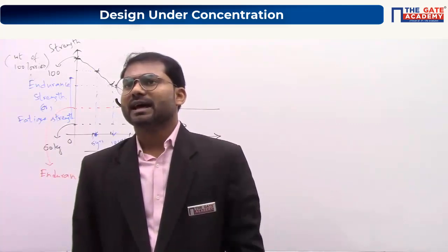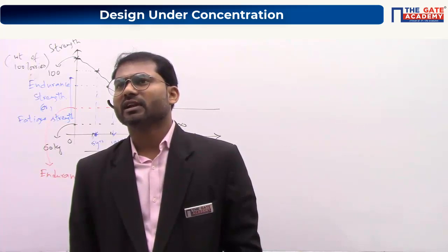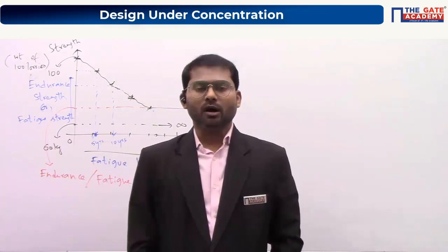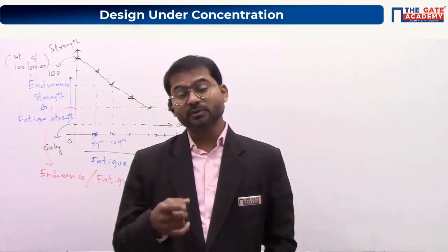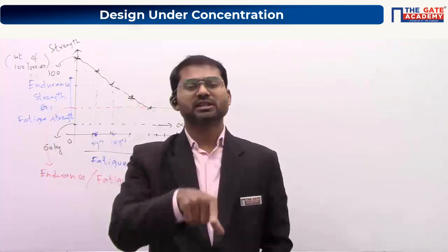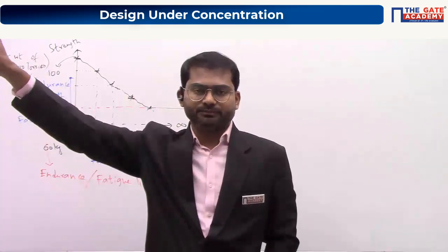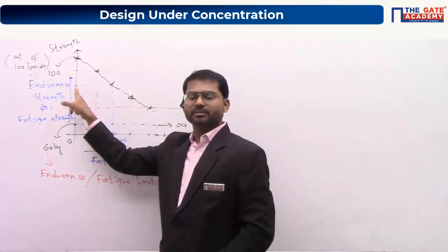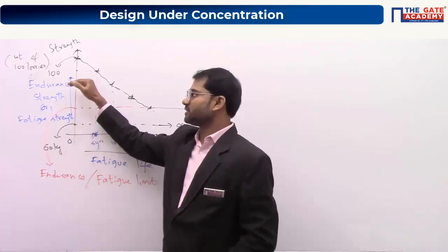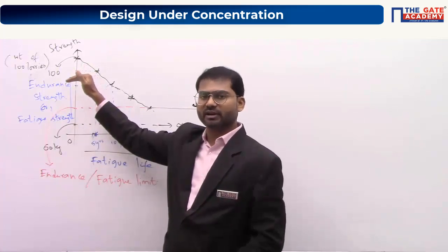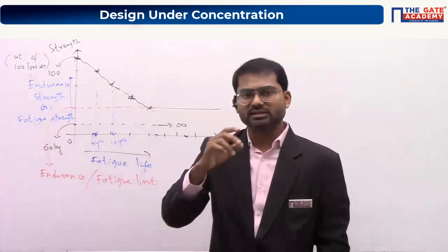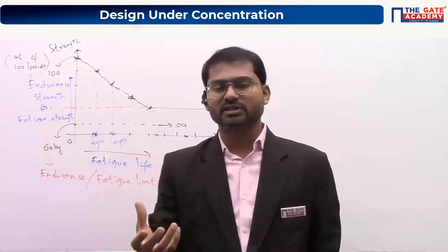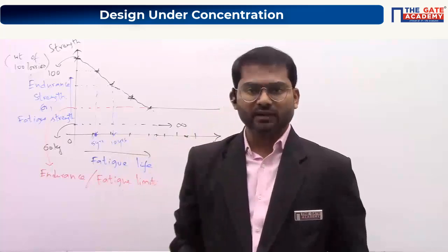It means a dynamic load bearing part of a machine can have infinite life, for example a propeller shaft. Makesh, what I'm saying is, if your component which is experiencing dynamic load is experiencing a stress less than its endurance limit, then it can have infinite life. Are you able to understand? So here, the life depends upon the stress that is actually being applied. If the stress applied is higher than the endurance limit, then you cannot have infinite life. If you create a scenario where the stress produced inside the component is far lesser than the endurance limit, then you can expect infinite life.